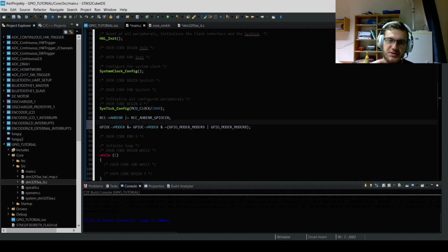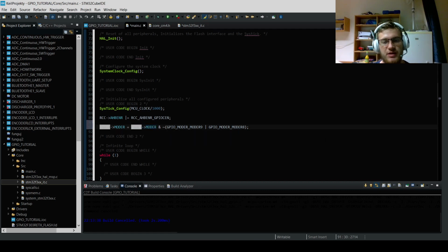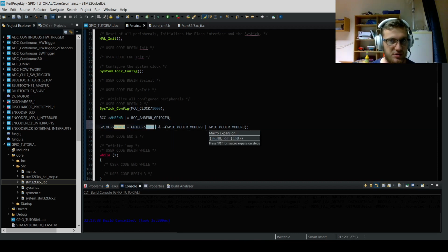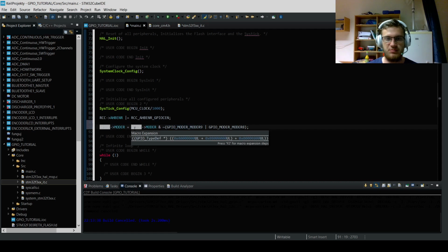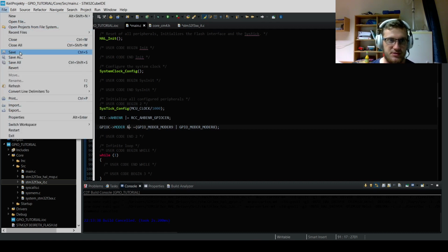Basically what I'm doing is, sorry, I will delete this. This register, which is an integer, for example, over here is 1, 1, 1, 1. This register is entirely 1, but I will make sure that on these positions there will be zeros. Because there is a NOT, which makes these two zeros, and AND, basically this is 1, this is zeros, it will equal 0. Simple. And again, let's make it shorter. Boom. So this is our mode register.